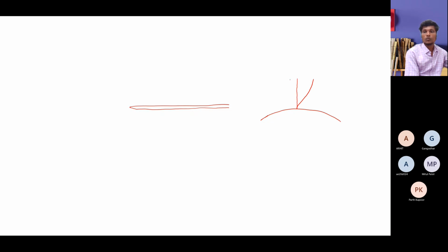So if your velocity profile is like this at some point, your flow cannot move any way because it is almost zero velocity here, as dv by dy equals 0. So it can only do one thing, which is separation from this surface. So from this point, your separation occurs because it is purely due to the viscous effects.